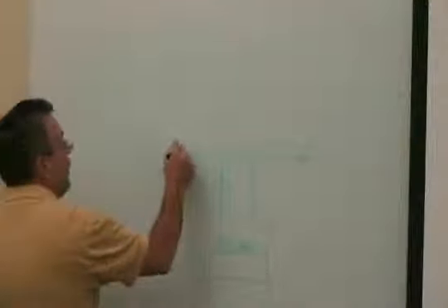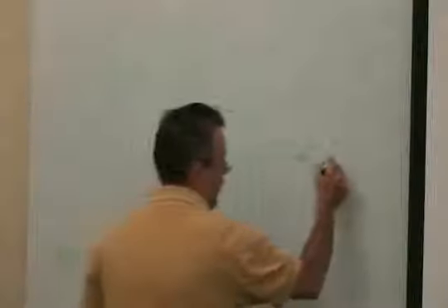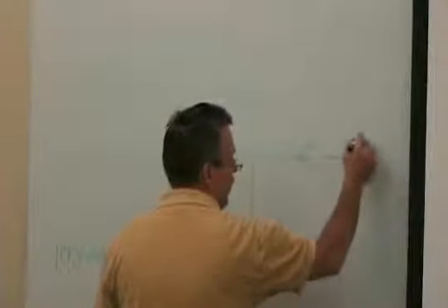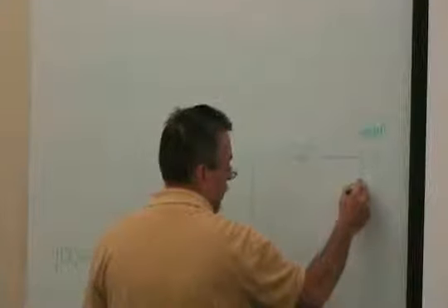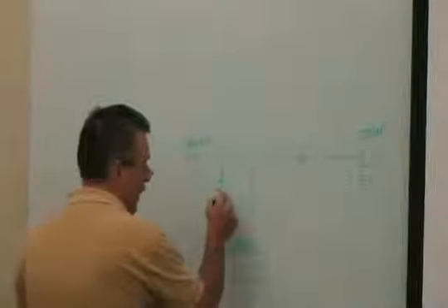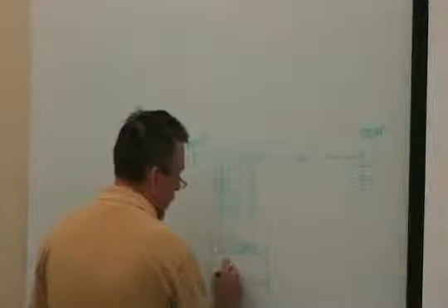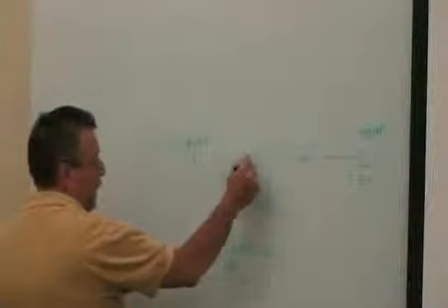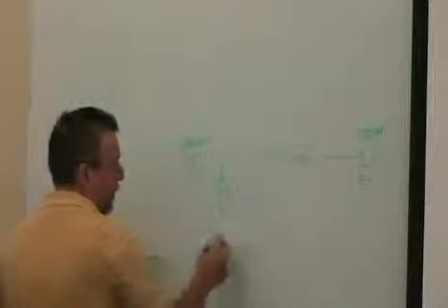I've got a temperature sensor right here, and maybe a temperature sensor right here that says, hey, I'm at 59 degrees. So I'm going to turn the pump on and activate the boiler. The boiler is probably going to produce 140-degree water. It's going to mix with that 59 here, 59 here.